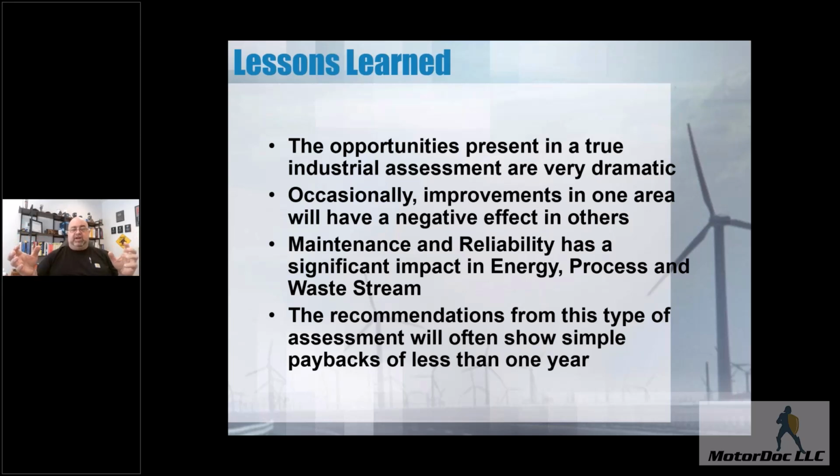They had somebody who ran across the street. There was a hardware store across the street, ran across the street, got an English bolt to put into a metric fitting and stripped it. And basically several times a week, sometimes once a shift, they ended up having to repair the machine over and over again, and they'd lose anywhere from 30 to 60 minutes. Fixed it with a drill and tap. So that was it. Which basically I had in a toolbox in my car, so it didn't cost anything to fix it, and off they went.